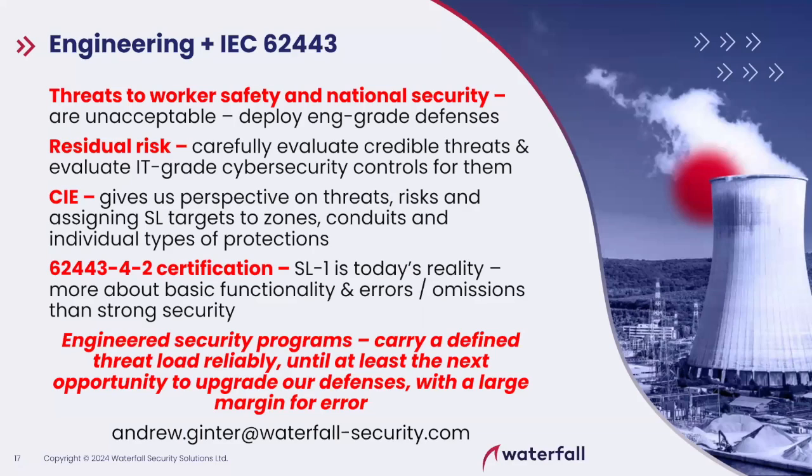Now, IT may not be happy with that. They might want you to put a unidirectional gateway between the PLCs and, let's say, a DMZ that they can control, because they need to protect the information, not just the safety. The engineers are tasked with protecting safe operations. IT is tasked with protecting valuable information. We need to cooperate. So, that's another use case that we see increasingly: OT to, let's say, a DMZ, to the internet through a unidirectional gateway, through some kind of network engineering to keep the OT network safe in spite of the cloud connection, not running the cloud connection through 7 layers of Purdue and confusing what's going on with the Purdue model. That was a long answer. Sorry.